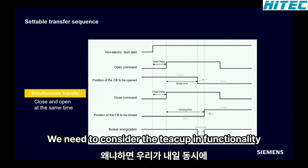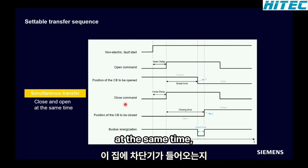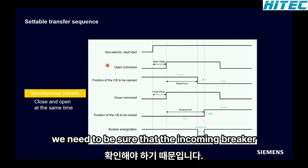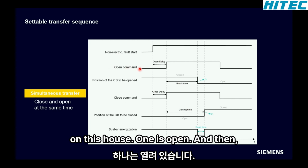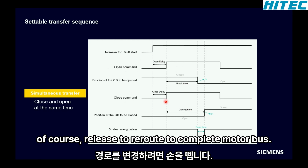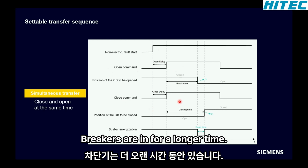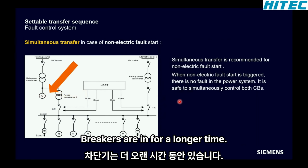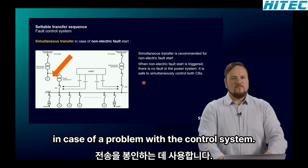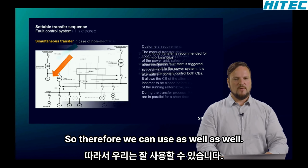And for that, we need to consider the decoupling functionality, because when we send the open command and the close command at the same time, we need to be sure that the incoming breaker from the source 1 is open. And if not, then we need to trip the other breaker. So then, of course, we lose the complete motor bus, but it is absolutely forbidden that both breakers are in for a longer time. We also use the simultaneous transfer in case of a problem with the control system.